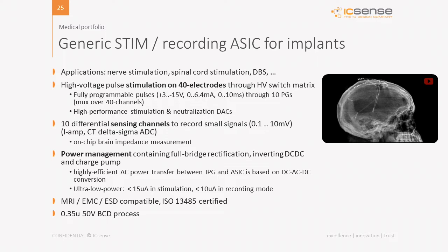On this chip, we have developed high voltage pulse stimulation for more than 40 electrodes, all connected through a high voltage switch matrix, and all these pulses are fully programmable. So also here, there's sufficient flexibility to play with the different pulses according to your therapeutic needs. On the other hand, there's also the sensing. We have implemented 10 differential sensing channels to record small signals.